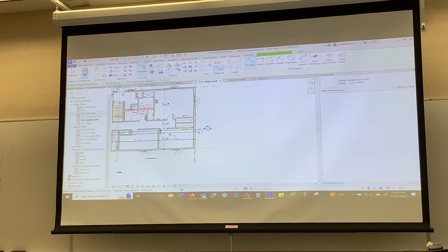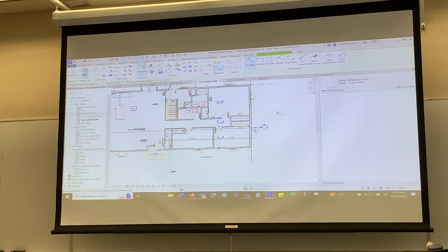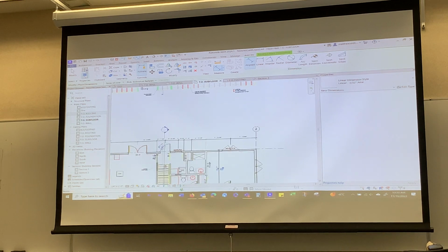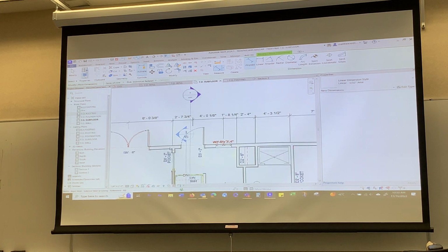If you give me that, that tells me you know how to use the tool. To interior and to exterior. But if you, well, it's your choice. Myself as a framer, I like it, most stuff snapped to the outside. The key is consistency. So when you run a string down a wall like that, you want to be picking the same side of the wall all the way, unless there's a good damn reason not to. Because it just makes it so much easier, okay?